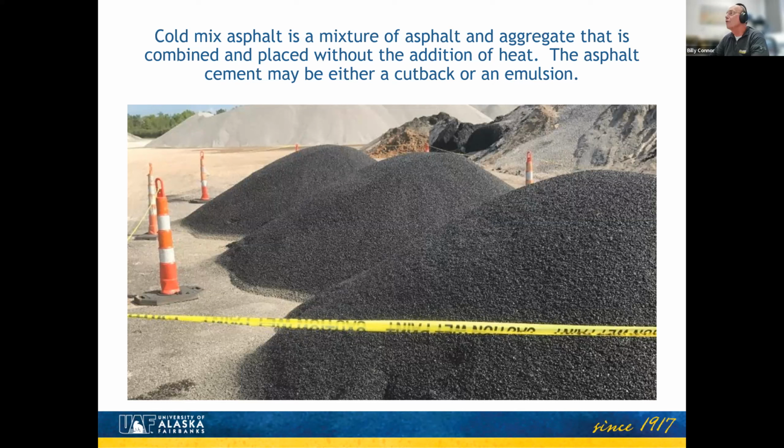And the reason is it breaks. In other words, the water and the asphalt separate from each other once it's mixed, and it becomes a solid fairly quickly. And then you just let it cure out for a bit, but you can put traffic on it while it's curing out. The cutback takes a while for the volatiles to come out. And in fact, depending on the volatiles you use, those volatiles can be in there for as much as a year,